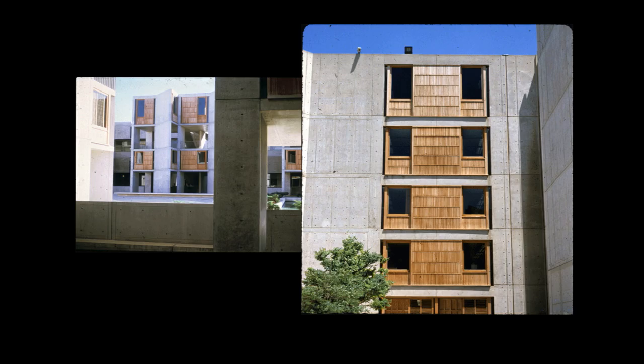walls that you need in order to support the concrete that's being poured into the formwork, you can imagine that there's going to be a lot of structural support that's needed for those walls. And you can go about that in a couple of different ways. On the one hand, you can build up a lot of structure on the outside of the formwork to stop the concrete from sort of pushing the formwork out.